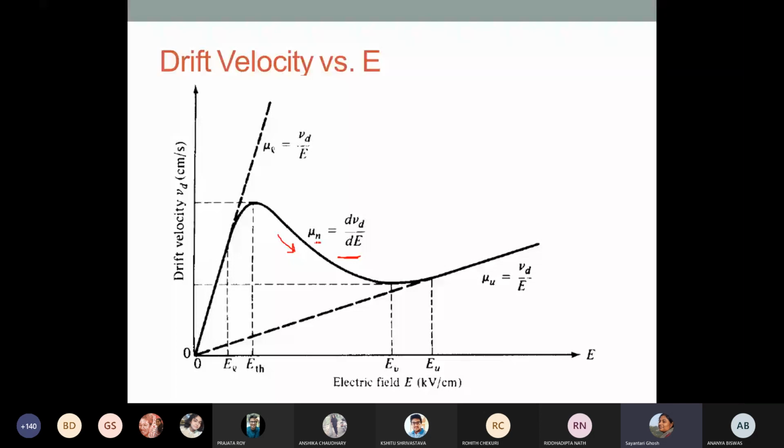Okay, so as soon as you see that there is a portion where you have this negative mu, you can associate this directly to that equation of Q where charge accumulation was taking place, right? That was the point where we stopped in the last class, and you have seen that with time, the charge will increase exponentially if you have mu negative, which you have for quite a large region in these materials where this particular behavior is happening.